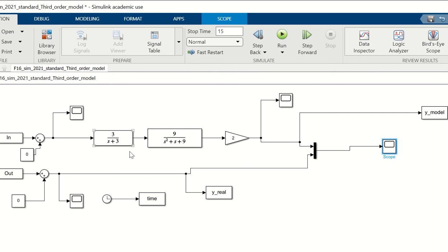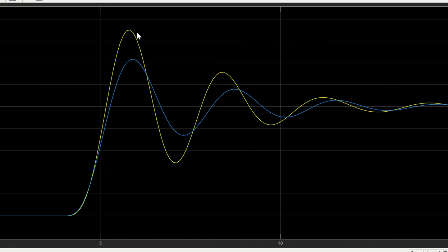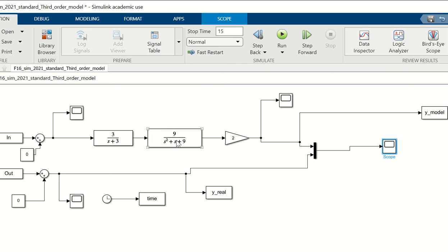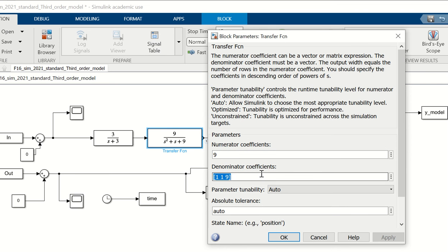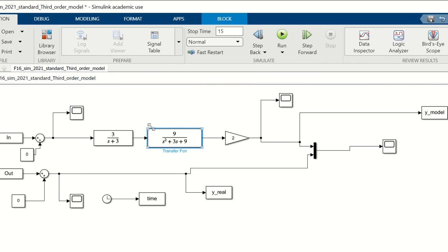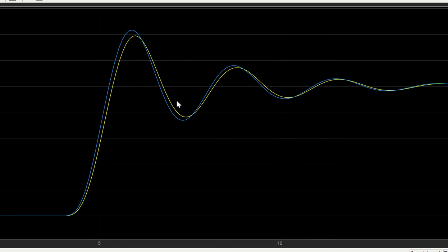Better, when you're closing in on these, if we go back to this, we can pull this signal down a bit by increasing the damping ratio. So probably better off going for that number first. Lost my order of doing things here. So we made that a 3, for instance. Then run it again. This is increasing the damping. So that's then brought these two signals more in line. Now it's easier to adjust the yellow one. So I got the order wrong. Should have done DC gain first, frequency second, damping ratio third, and then go for the parameter last, the 10 or whatever it was.